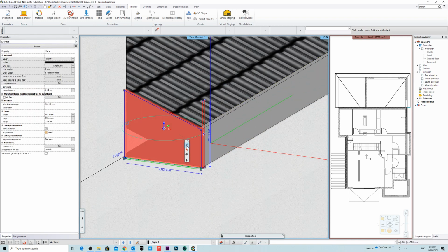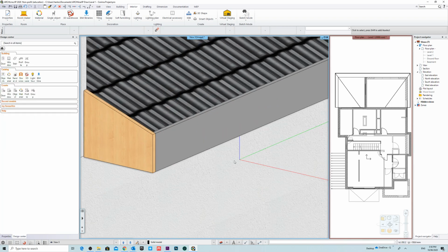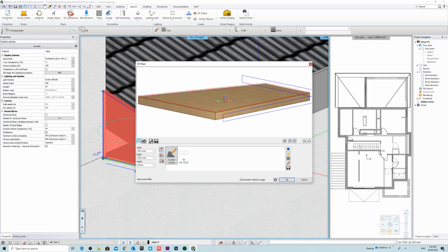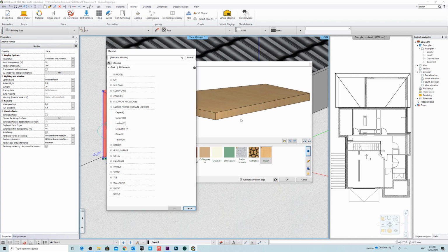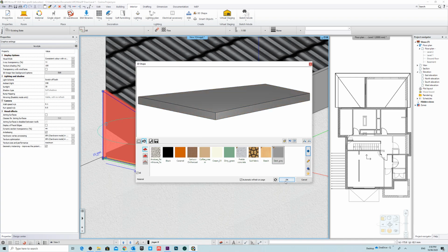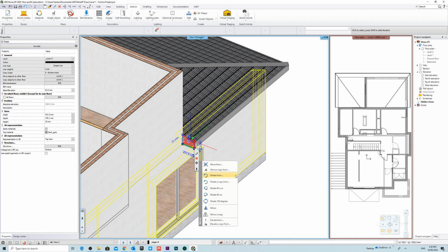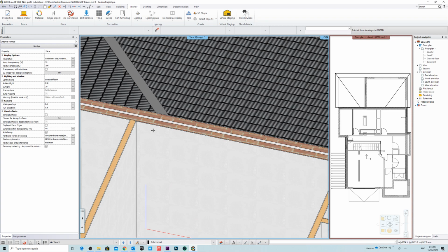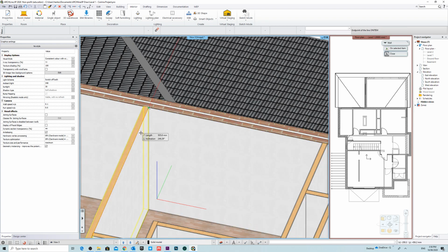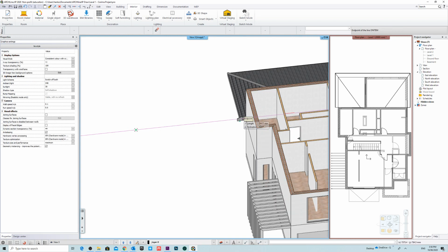And we're going to click on this, click on it again. And you can see here, height, we'll just make that 25 mil. And we're just going to change the material as well. So we'll go to gray, dark gray, just click OK. Right, so we have that there. And now I'm just going to mirror this across. We don't have to recreate that. I can just go mirror, copy, just select literally anywhere like that. And I'm just going to move it a little bit back into place.